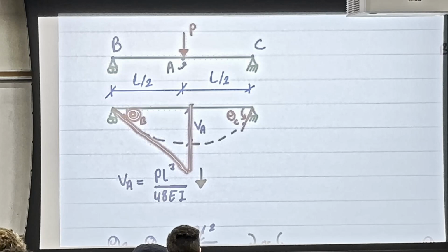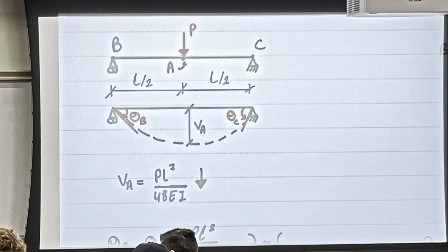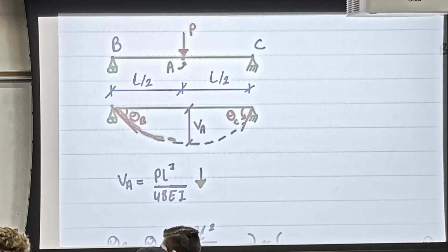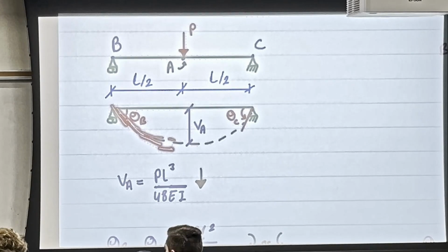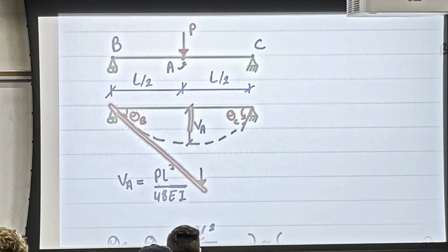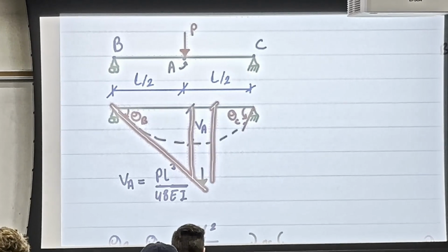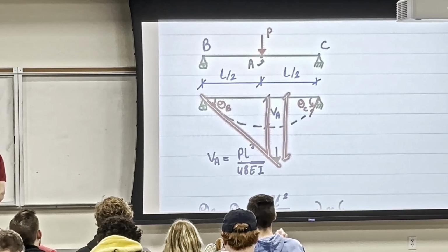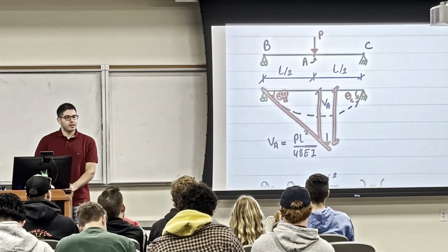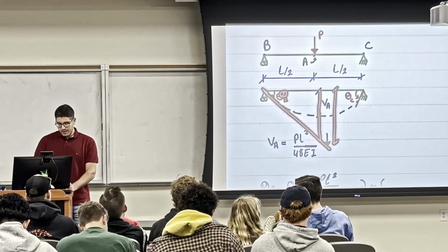The reason why this is wrong is because within the beam span, you have a curve, you don't have a line. And at each point on a curve, you're going to have a tangent that is different. So the reason why you can't use trig here, instead you use the equation, because if you use trig, imagine you make a curve, you make a tangent here, and then you need to close the triangle, right? So you are estimating a very big deflection that is not real, okay? And you're also getting a very big angle that is, I mean, an approximation.